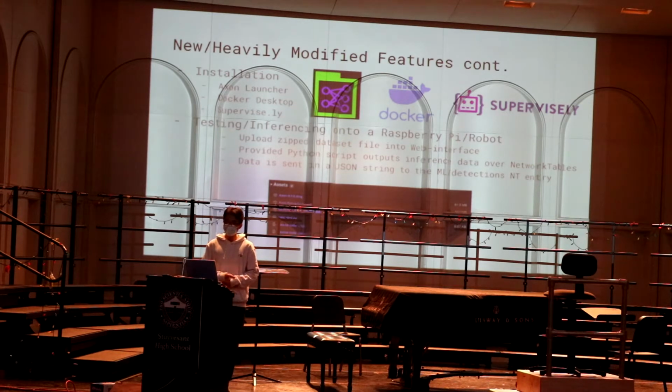And after all that, you can test it by uploading a dataset file into the web interface of, say, something like WPILibPi, which is for Raspberry Pis. And for robots, the data is sent over in a JSON string to the network table entry for machine learning.